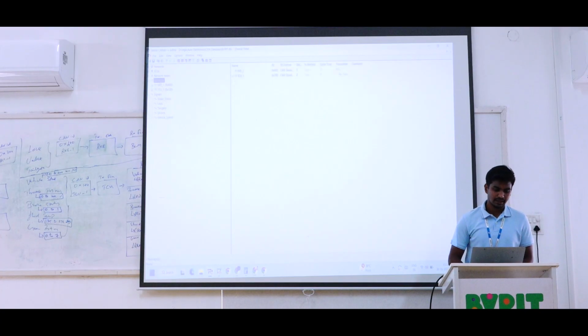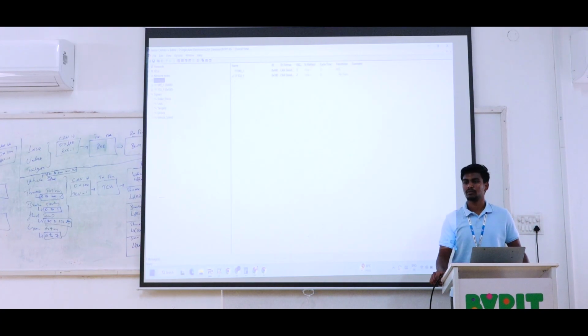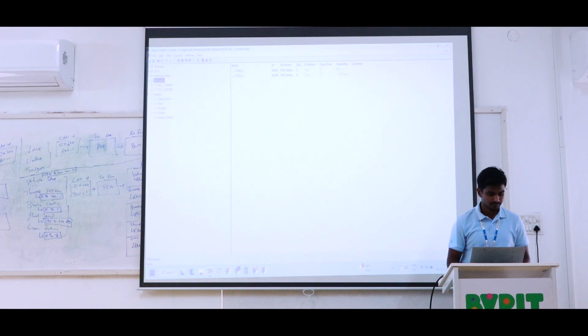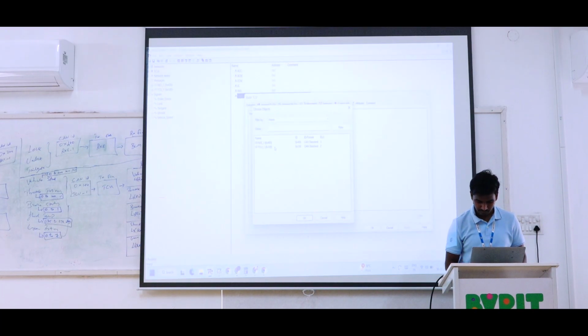Okay. So initially we were just mapping all the signal values from one ECU to another ECU. For example, go to network nodes. I'm going to do the mapping for the transmission. So TX messages added to the ECU. Now the TX signals, vehicle speed and brake status, are added, so it is a transmission message. Previously for the ECM we were using a direct receive signal, and all the signals from the TCU message will be received here.